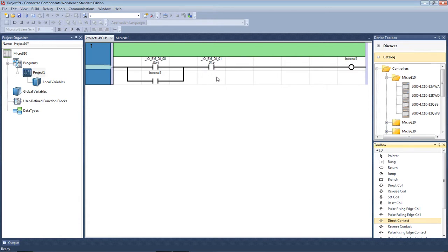So when we switch this on, our normally closed stop button in the field will signal this to actually close. Same with overloads and so forth, they will show up as normally open. So that's the difference between our relay logic and the logic we apply to our circuit diagrams.